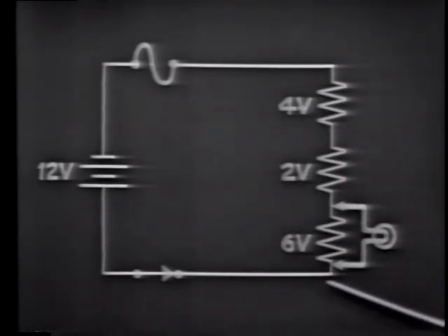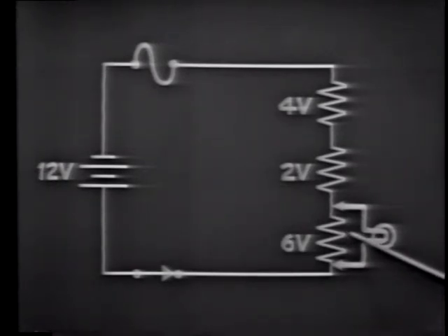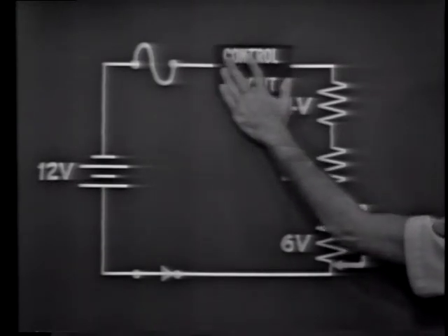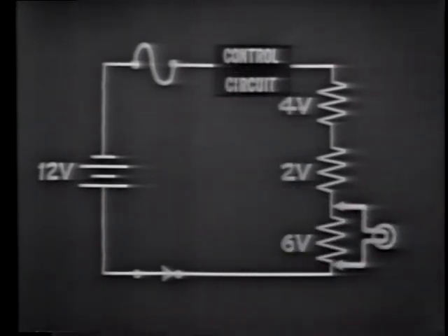Keep in mind that the voltage change is caused by a decrease in total resistance, which allows total current to increase. To get accurate voltages, you must know the amount of load you're placing on the circuit. Remember also that special circuits are used to maintain a constant voltage under varying load conditions.